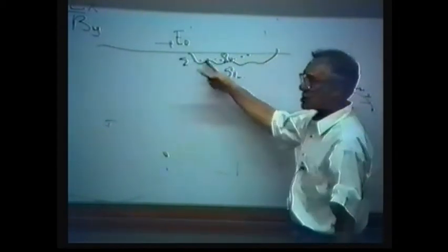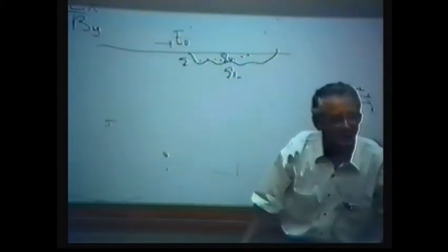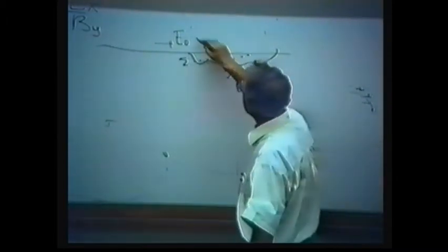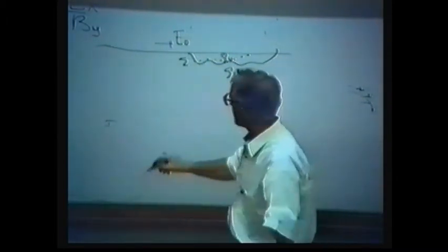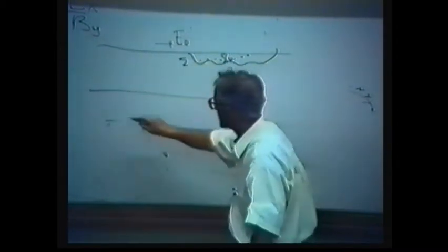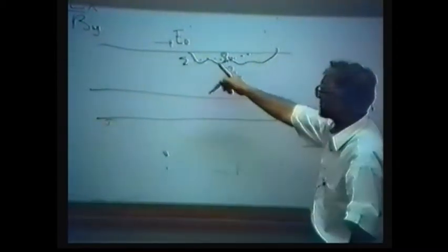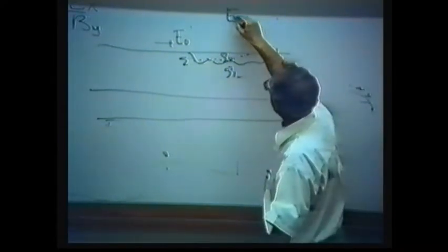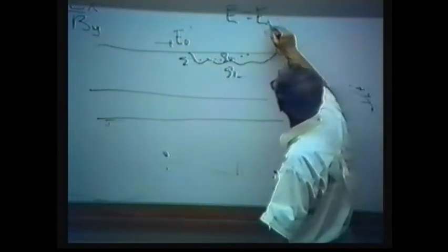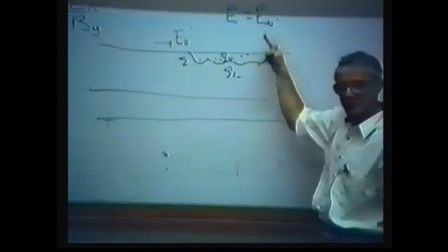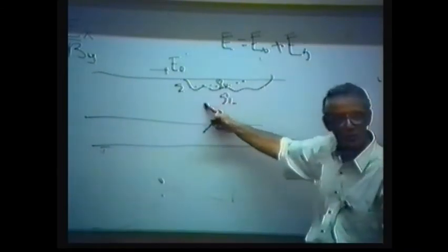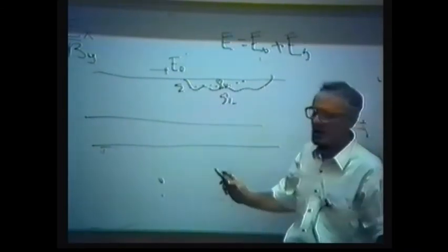And these charges do create an electrical field. Suppose we have a horizontally layered medium, and we have this inhomogeneity. It turns out the electrical field consists of two parts: the field in the horizontally layered medium plus the field due to these charges.